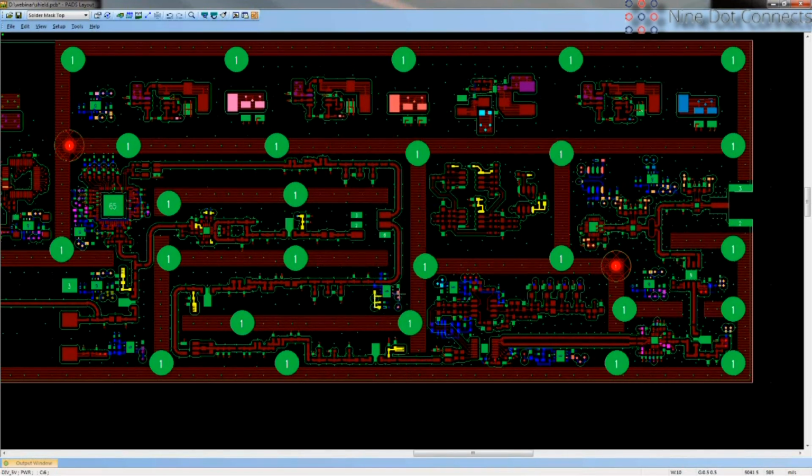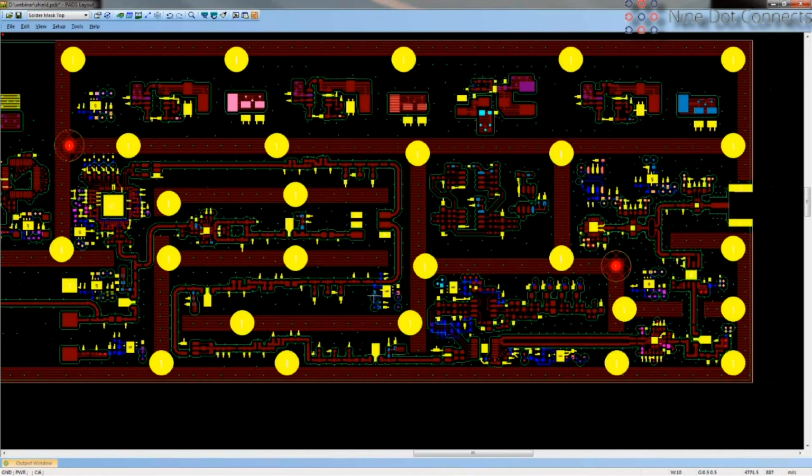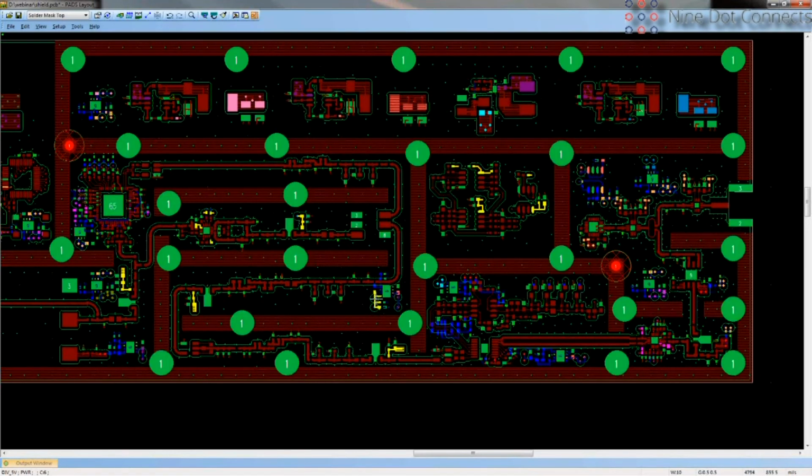Here's the input power that's highlighted, and then the output voltage that I'm trying to highlight right now. So it's always a good idea to take your power supplies and other noisy circuits and put them on opposite sides of your boards, if you've got the luxury of the room to do that.